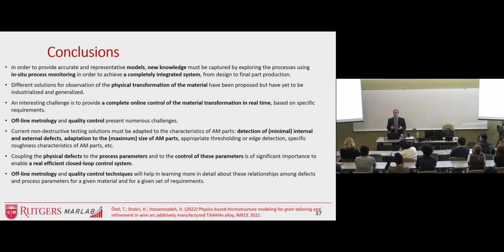Also, some of the defects come from thermal stress gradients, like warping, distortions, etc. But a lot of times those defects are identified, as you mentioned, by post-process measurements. And it takes a lot of destructive testing to be able to reveal those defects. Some of the defects you can see on the surface, and I showed that at the beginning. But for example, it requires scanning electron microscopy to see the defects, and you cannot do this in the process.